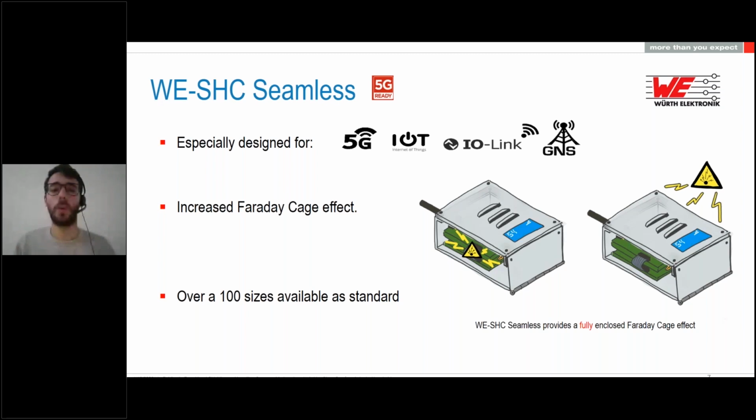As we are going high in frequency, and I don't want to get too much into the technical stuff for this short presentation, the slots and the holes that could be critical for our device are becoming smaller. Why? Because the higher we go in frequency, the less they need to be conductive in order for noise to be radiated through some conductive part.